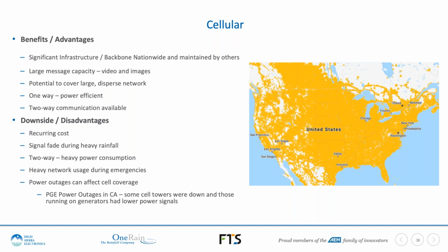But if you have sites that are spread out tremendously, 20, 30 miles, and not a dense network, it doesn't really work in an ALERT type environment or a SCADA type environment. But cellular, given that wide network capability, would be a good solution there.